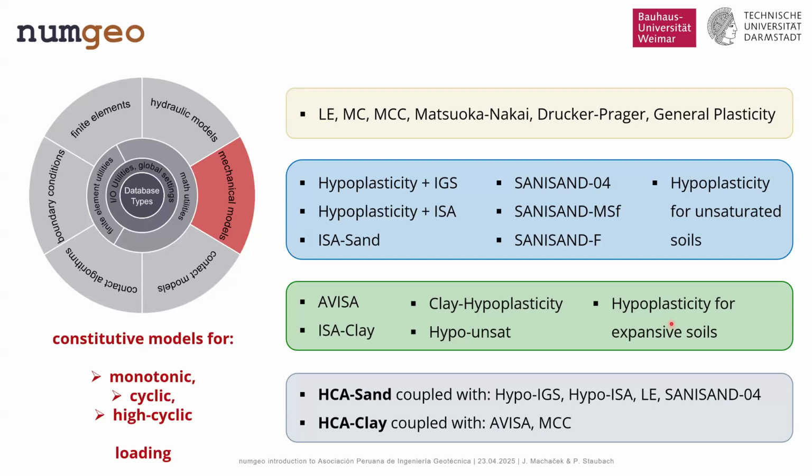Now, on top of these models, we have special models implemented that have been formulated to capture the behavior under high cyclic loading. When I'm talking about high cyclic loading, I'm talking about hundreds and thousands of loading cycles that are applied to a soil. For example, if you consider offshore foundations or train tracks, then they are subjected not only to a few hundred loading cycles during their lifetime, but to thousands and millions of loading cycles. And these loading cycles usually have a very small amplitude.